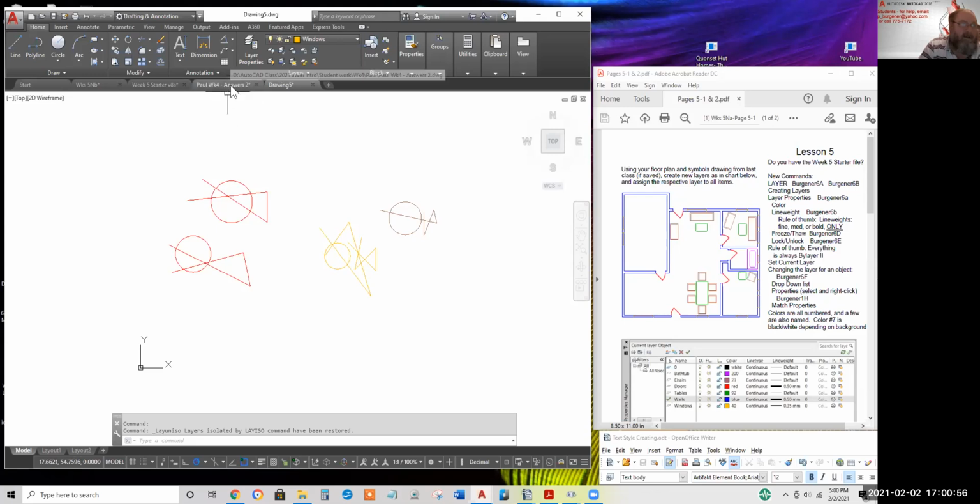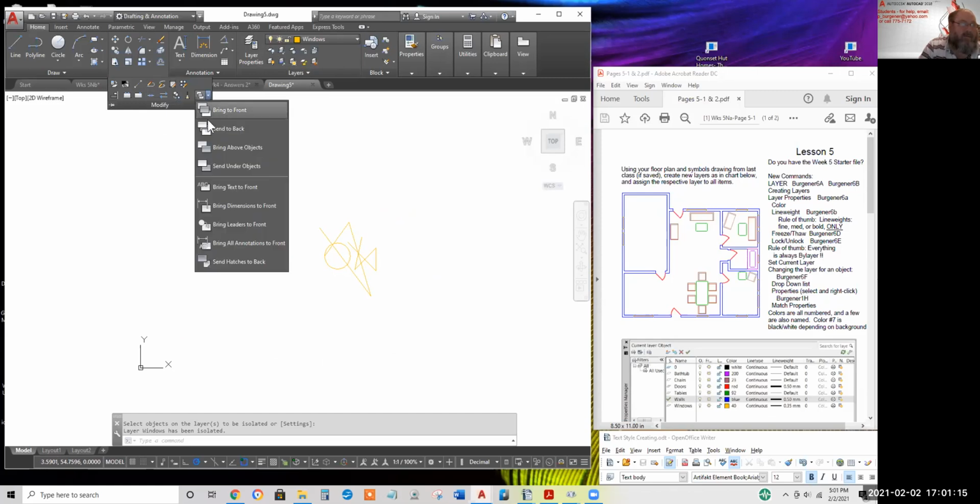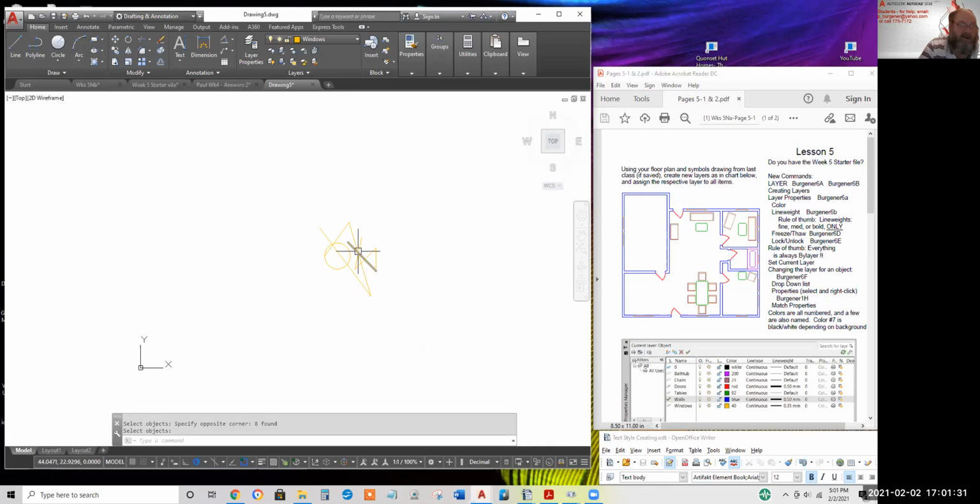Now when I overlay my drawings on top of yours, I want mine to be behind yours, I should say. So I might click on an object of your stuff on layer 0 and select everything. Here's the move to front and move to back list. When we get into hatching, that becomes important. I want to bring your stuff to the front or my stuff to the back. Since, say, yours is the windows, I'll click bring to front, select your entire stuff, and then, kind of like bring to front in PowerPoint, you can have different symbols on top or behind each other. So anyway,